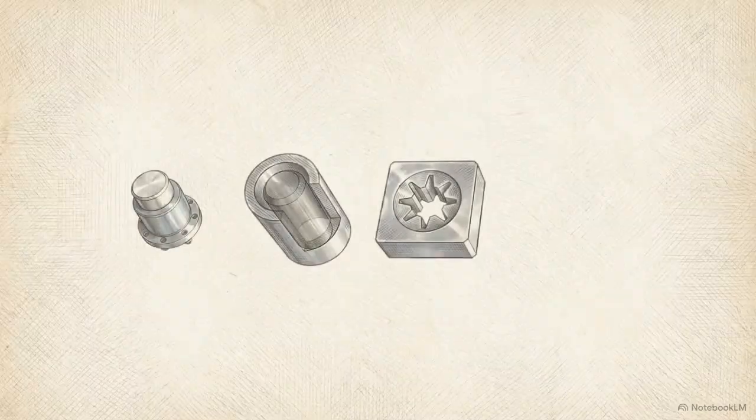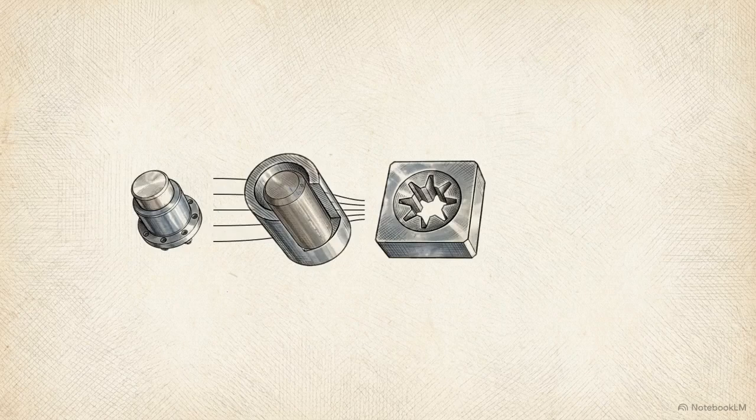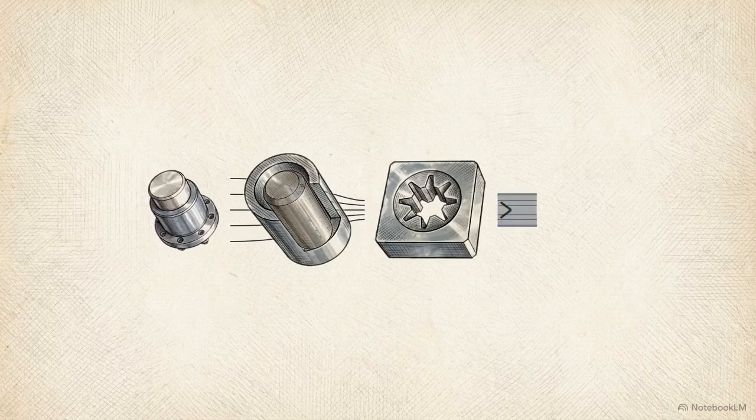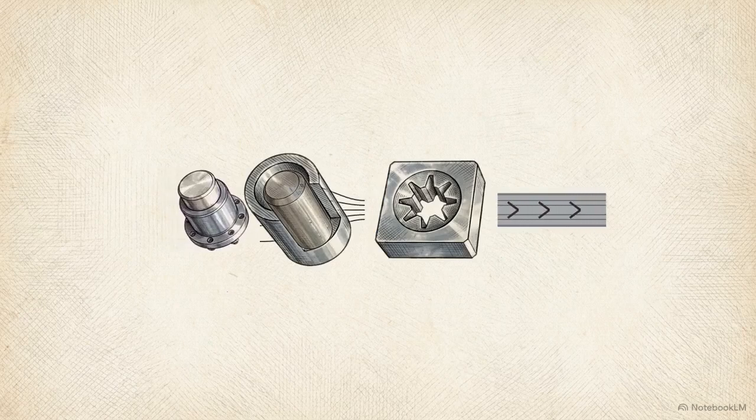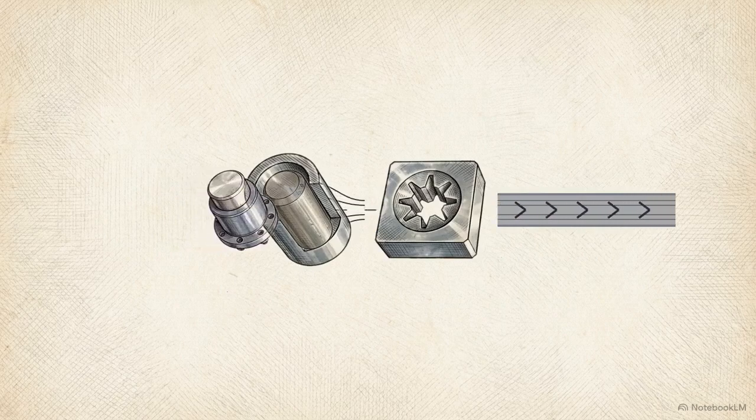The most common internal failure is center burst, or arrowhead fracture. When die angles are too steep or reductions too low, internal flow lines pull apart, creating hollow fractures in the metal's core that are invisible from the outside.